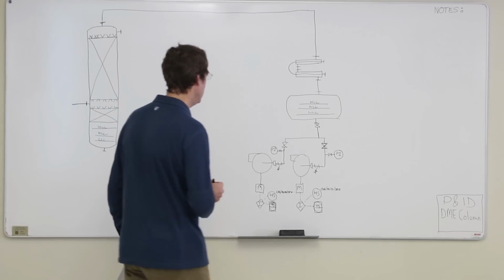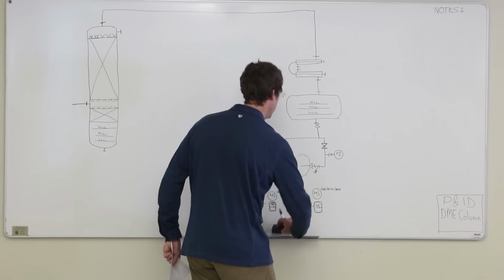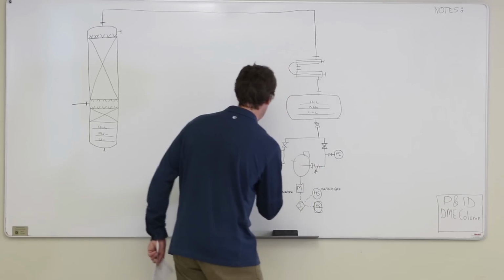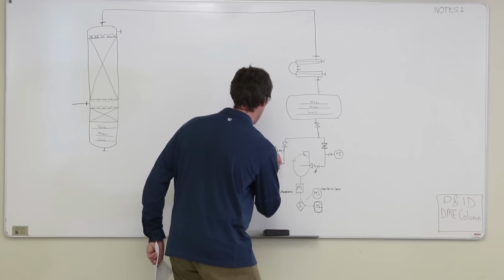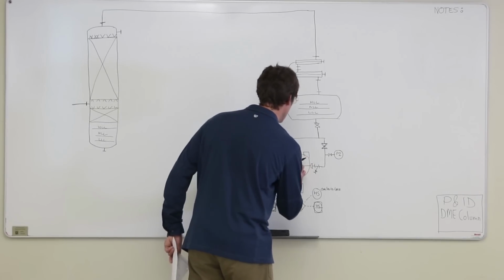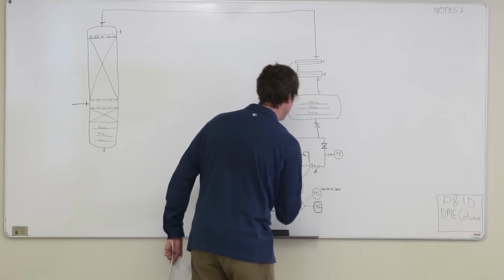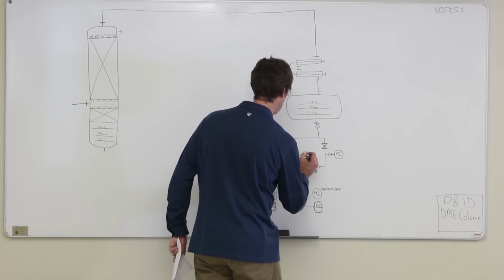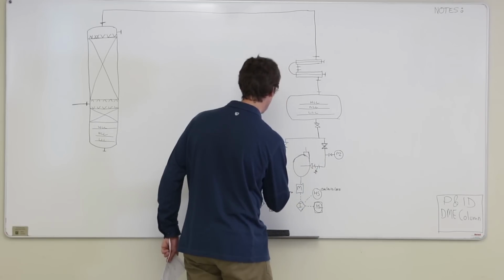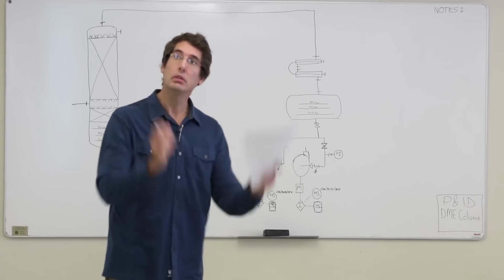Okay, and then the other, oh, I screwed up. I switched the direction of my pumps around here. There we go, that'll make life easier for me. So some people draw pumps vertically like this because the discharge on most pumps actually is off the top. And some people hate that because that's really the standard for drawing a fan. So I'm going to use this as the discharge on my pump. And I need a reducer installed backwards.